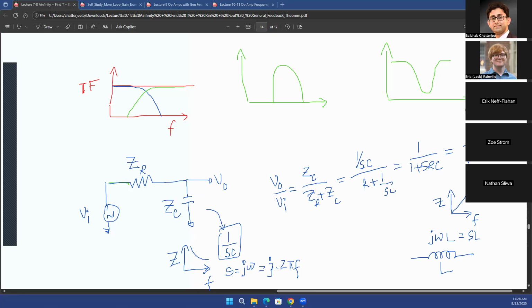Now what is interesting here, that from your 3111, you also know something about time constants, right? The RC time constants of any resistor capacitor circuit. What is the RC time constant here? As you know from the name, RC time constant is just R times C. From the RC time constant, you can also find out the bandwidth of the system. So the bandwidth of the system is 1 upon RC. Again, many of you are already familiar with the RC time constants and concept of bandwidth.